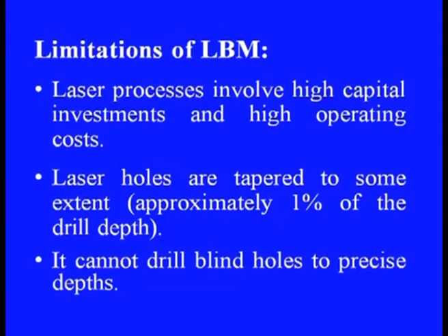Now, let us look into some of the limitations of this process. Laser processes involve high capital investments and high operating costs. Laser holes are tapered to some extent, approximately 1% of the drill depth.